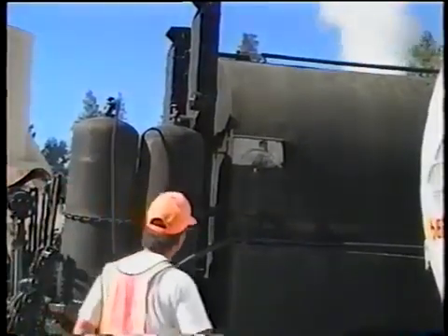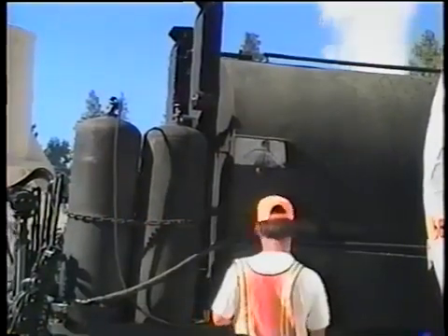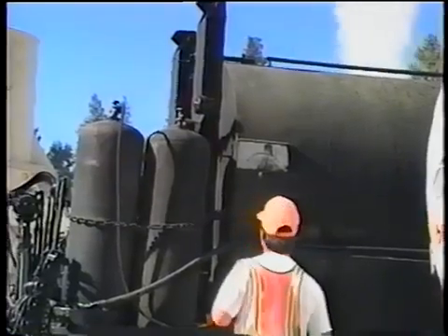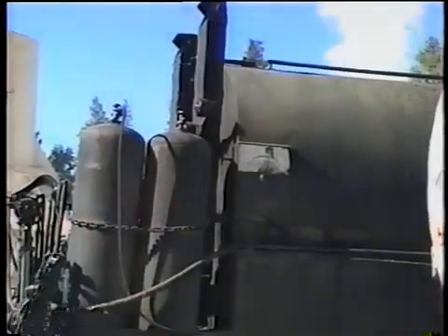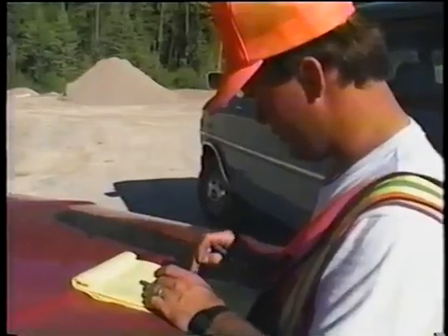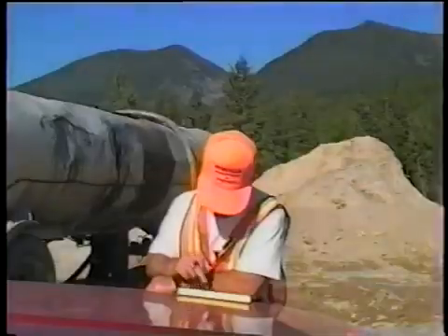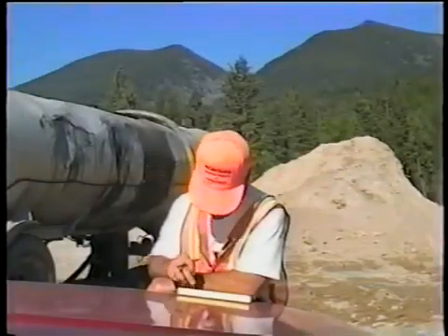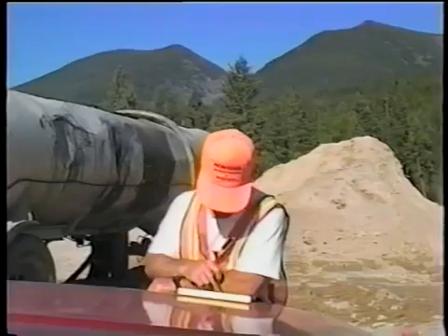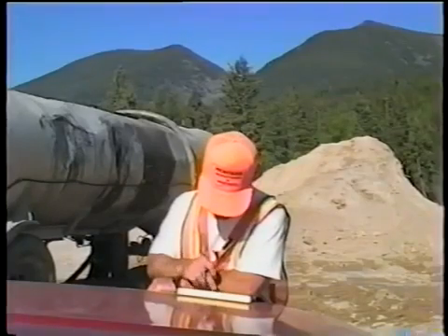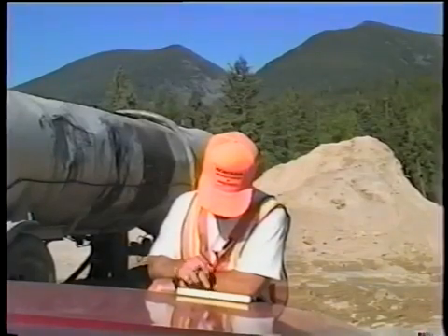After the material has been applied, be sure to record the number of liters remaining so you can calculate the application rate. To do this, you divide the number of liters of tack applied by the area covered. The length of application times the width in meters. The rate is so many liters per square meter.